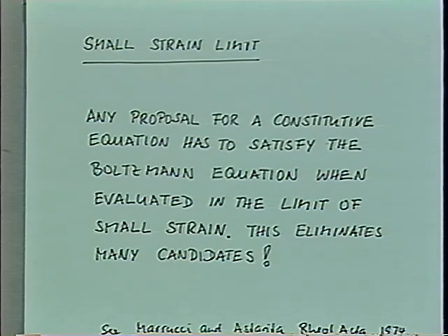There are especially constitutive equations for which the strain rate is used to modify the relaxation modulus and the relaxation spectrum. So whenever the strain rate is used, which was by intuition one way of looking at shear thinning, to obtain a constitutive equation for large strain, then you're losing the ability to go to the linear viscoelastic limit in the limit of small strains.